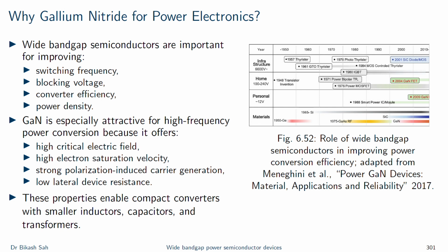Technically, in power electronics, we are always trying to reduce losses and volume, increase switching frequency, and improve thermal utilization. GaN is important because it improves all these dimensions at the device level. Its wide band gap, WBG, supports a high electric field before breakdown.